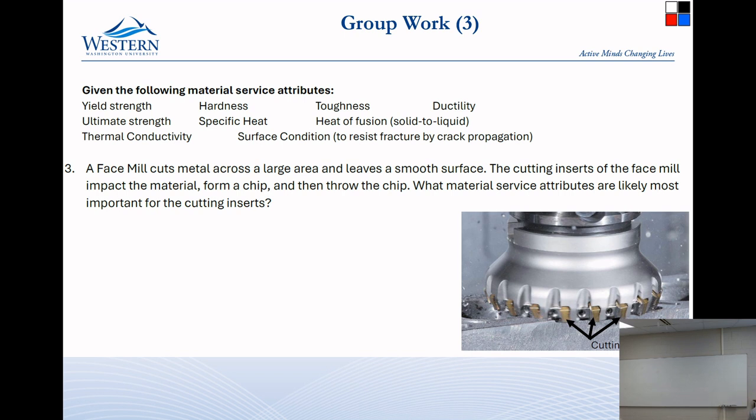That is absolutely true. Oddly, this is a place where thermal conductivity matters a lot as well, because it generates a hellacious amount of heat right there at the end. And you have to try to get that away from that end as quickly as you can. Otherwise, you will weld the material that you're trying to cut to the end of the cutting tool, and that doesn't make a very good cutting tool when you've welded something to it.